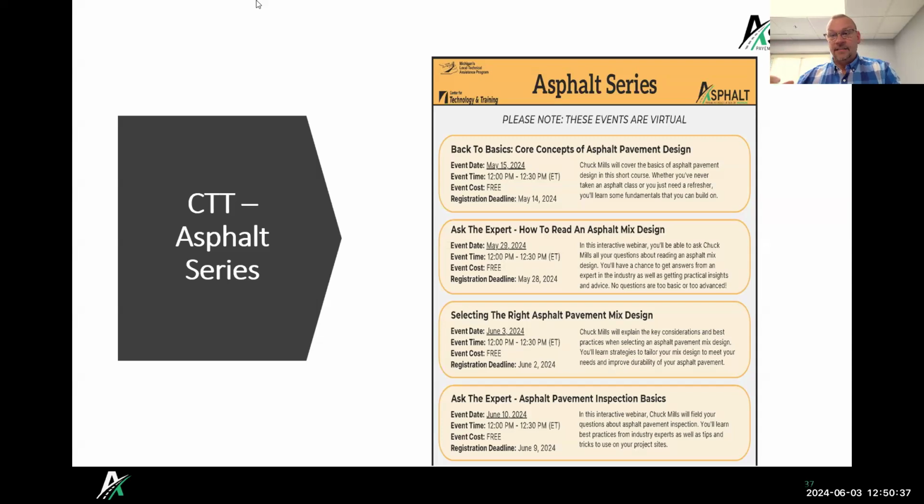You're going to have less asphalt content, and it's going to be a little stiffer each time you do that. But you should still be able to recycle that mix into the new mix. It may just be how you characterize that and account for the RAP in your mix. Maybe we have to add a little more virgin asphalt because the asphalt content is a little lower as you go. That makes sense.